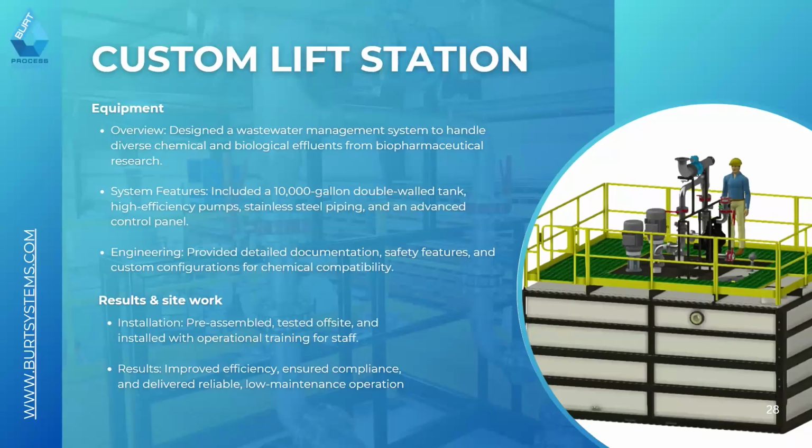Now, from an ease of maintenance standpoint, extraction style pH probes, ones that are basically tied into a valve that either goes through the sidewall of the treatment tank or the U-trap or the circulation line, are typically ergonomically easier than having one mounted through the top. Where the tank is large, for example, in the picture on the screen here, with some 8 foot tall tank, a probe that has an 8 foot stem attachment is obviously more unwieldy to then take out and calibrate. So for most systems, I'd recommend more of an extraction style pH probe. But that's a very varying topic.